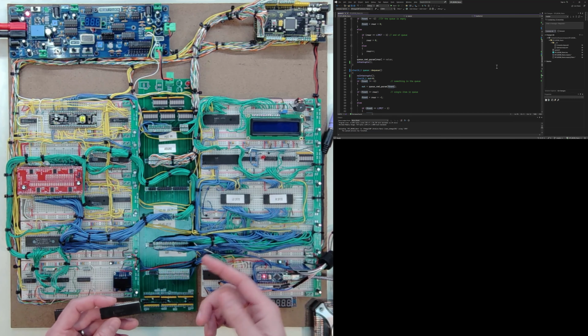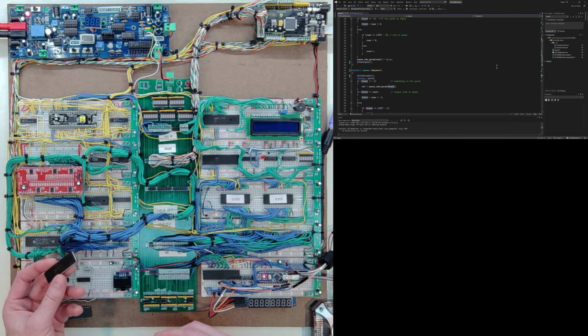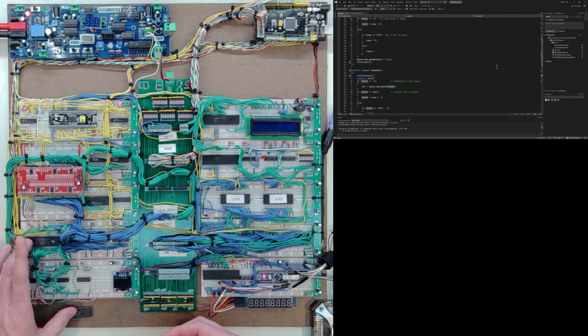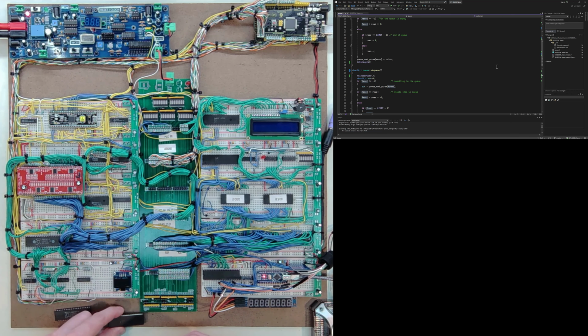So once I get the CMOS versions of the PPIs, I'll swap these out. But with that comment, I'd also caught that my 287 was a non-CMOS version. So I ordered CMOS versions. I got those. I pulled out the original and put in the CMOS version, and it really was not working, or it was flaky at best. So today I took a little time and tried to dig into and figure out what's going on there.